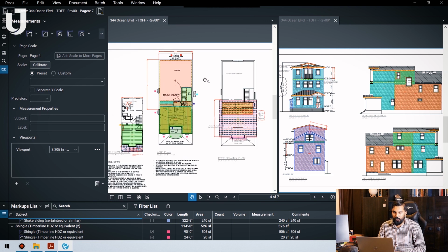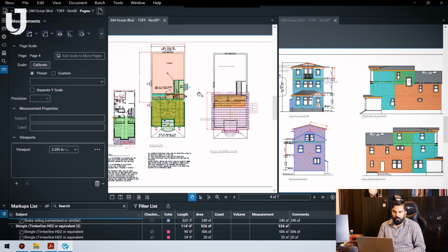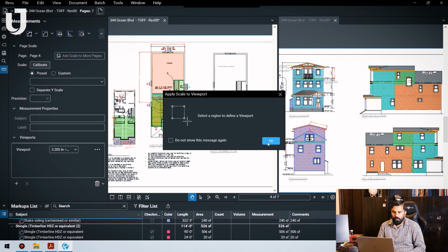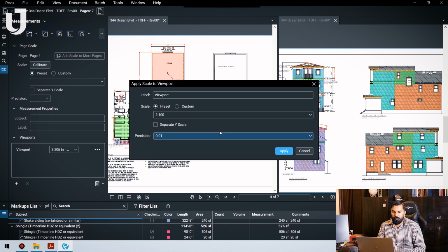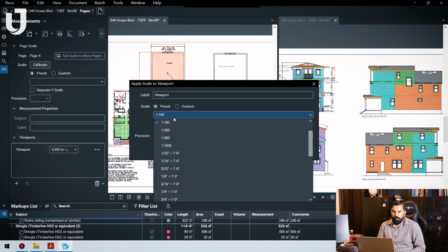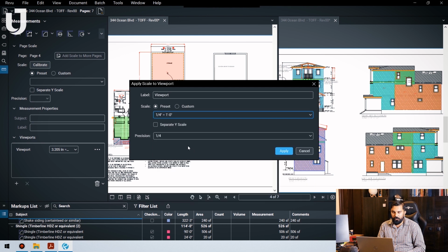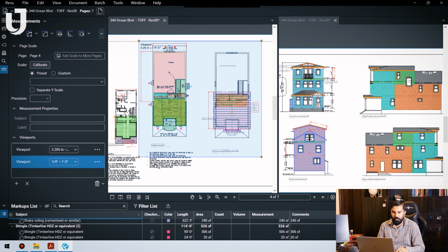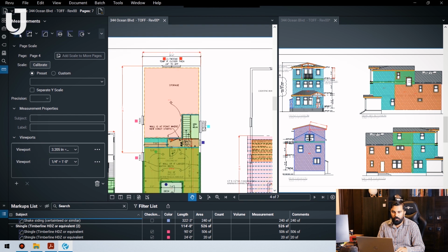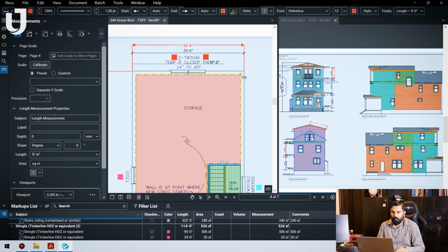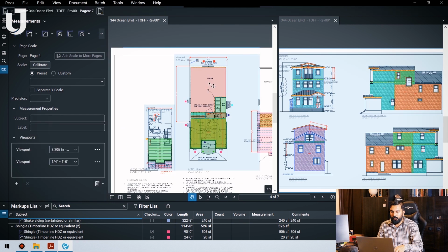See, we don't have the scale for this area. We just deleted it. We can re-add it and it will recalculate. If the scale is wrong, no need to redo the marking. You can just keep the marking there and then rescale it. The calculations will automatically adjust. The scale was already written, so we have put it in. So everything is updated. We can recheck like this. Okay.